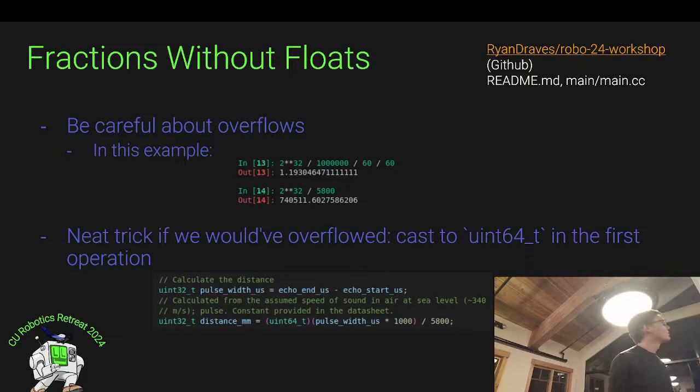Yeah, so the more zeros you add, the more arbitrary precision you're going to get, because remember that we're doing integer math here, so we're going to chop off whatever's left on that remainder, right? So if I add a bunch more zeros, I'm going to chop off some very small decimal value. In this case, for the sensor, 1,000, I just picked arbitrarily because it made the numbers look nice. Our precision here is definitely not more than a millimeter or less than a millimeter, so we don't really care as long as we're not chopping off a full millimeter worth of precision. So we have the time in microseconds, so by the time that we convert it, 1,000 just works out nicely. That's typically a value that you'll see, but if you need more precision, just add more zeros and make sure it doesn't overflow. Thank you. Yep.